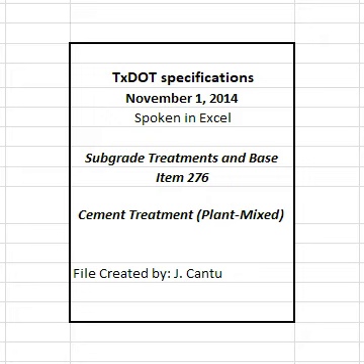Begin rolling at the low side and progress toward the high side on superelevated curves. Offset alternate trips of the roller. Operate rollers at a speed between 2 and 6 miles per hour, as directed. Achieve at least 95% of maximum density determined in accordance with TEX 120E when compaction is complete. The engineer will determine roadway density and moisture content in accordance with TEX 115E.